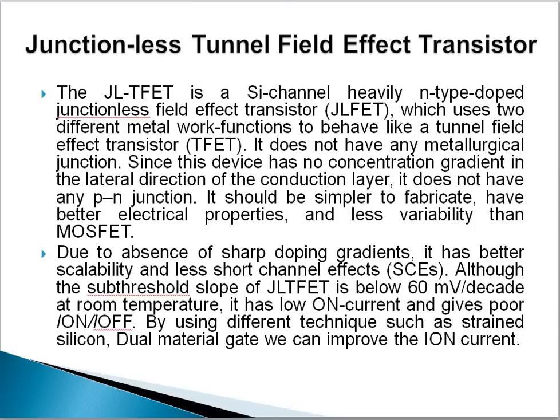Short channel effect like DIBL. DIBL is less in junctionless tunnel field effect transistor as compared to doped tunnel field effect transistor. Although the subthreshold slope of junctionless TFET is below 60 mV per decade at room temperature, it has low on current and gives poor Ion/Ioff ratio. But by using different techniques such as strained silicon, dual material gate, etc., we can improve the on current of the device.